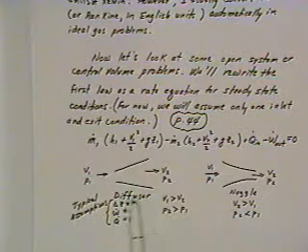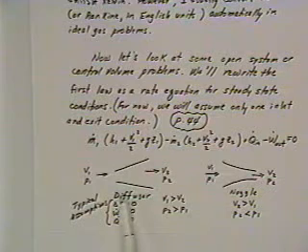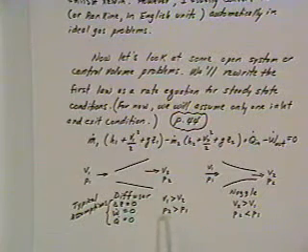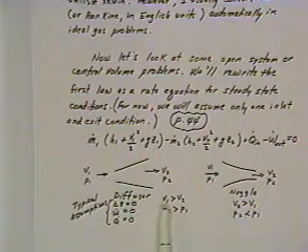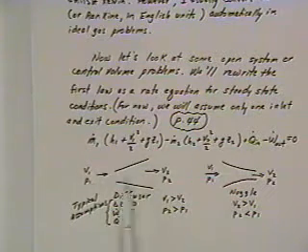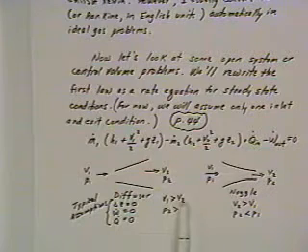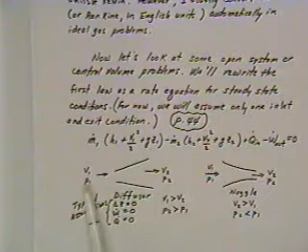And of course, in the case of a diffuser, your interest is in slowing down the velocity of the fluid or increasing the pressure, whichever way you want to say it. So what happens in the case of a diffuser is that with an entering velocity and pressure, V1 and P1, V2 is less than V1 and P2 is greater than P1.